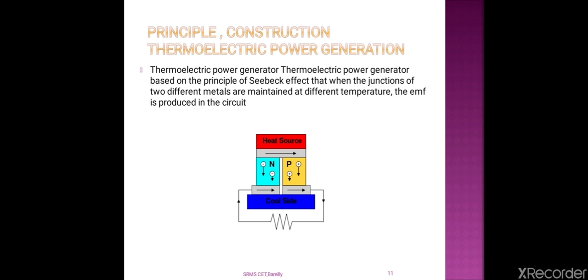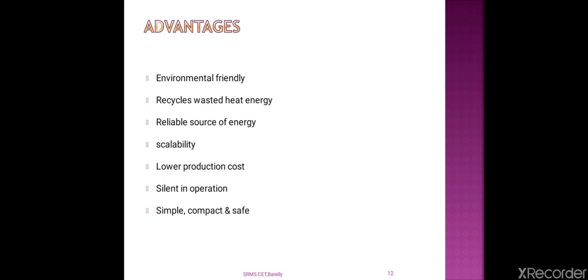In the steady state, the effect of the density gradient will exactly counteract the effect of the temperature gradient, so there is no net flow of molecules. If the molecules are charged, the buildup of charge at the cold end will also produce a repulsive electrostatic force to push the charges back to the hot end. So this is about the principal construction of thermoelectric generators.